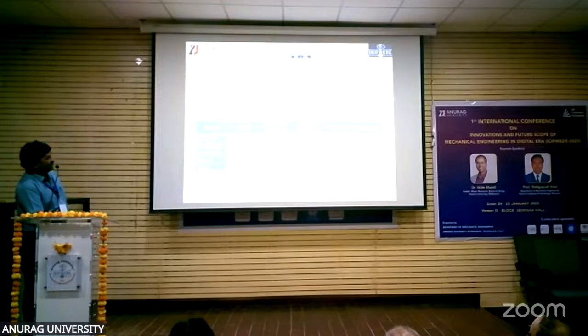For statistical validation, to check the results, we used ANOVA. In the validation, we got a p-value of less than 0.05. The p-values of pressure, weld time and amplitude are all less than 0.05.